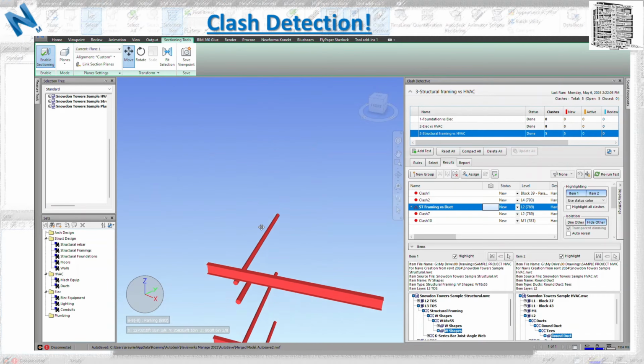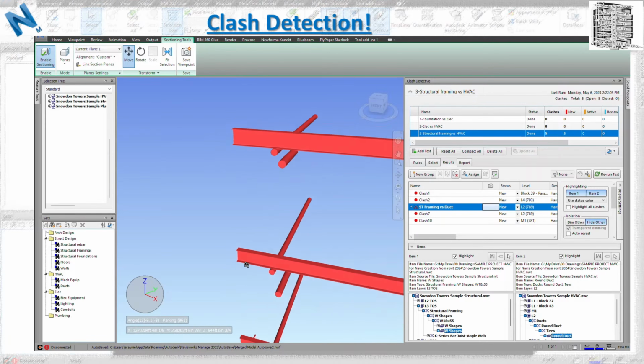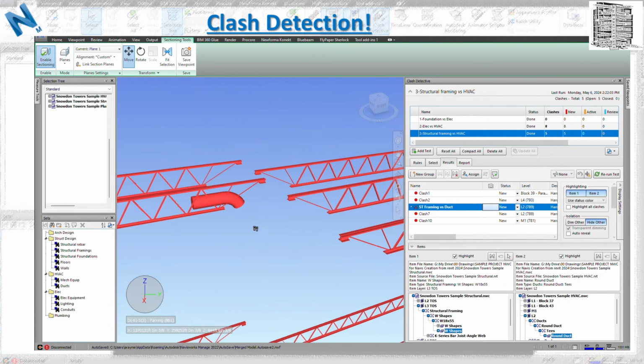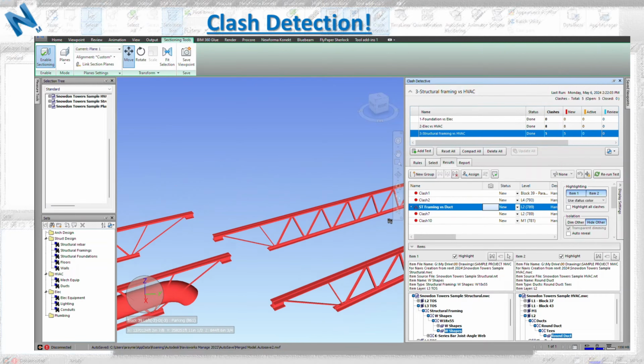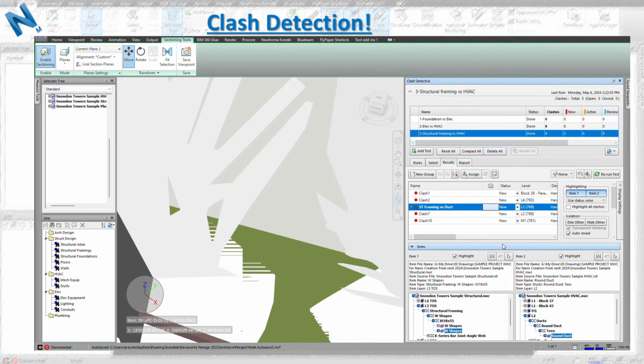The main thing in clash detection and coordination is that you need to do the analysis more. You need to allocate more time to analysis, like why they're hitting each other, is there a place to remove them, rather than spending time on grouping items, right? So grouping should be done fast. Put it aside, focus more time on analysis, and see how you can address the item.